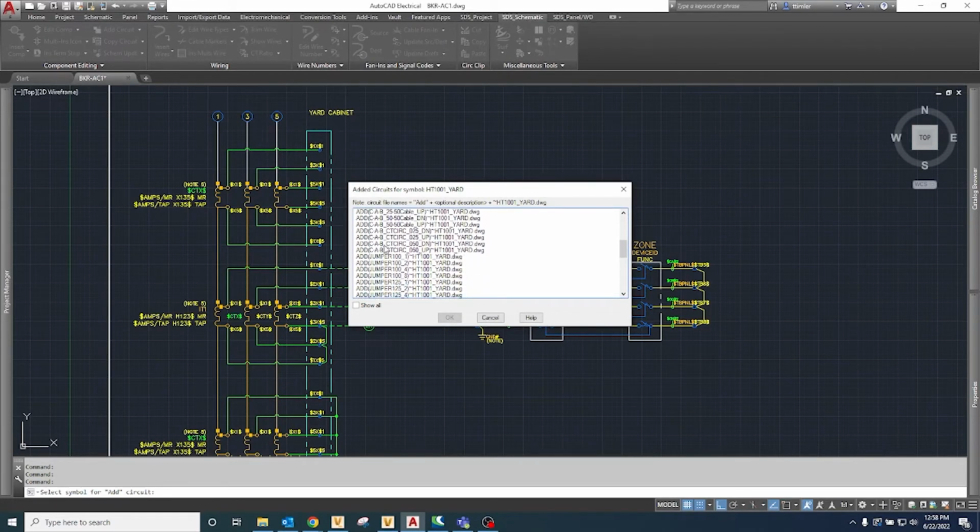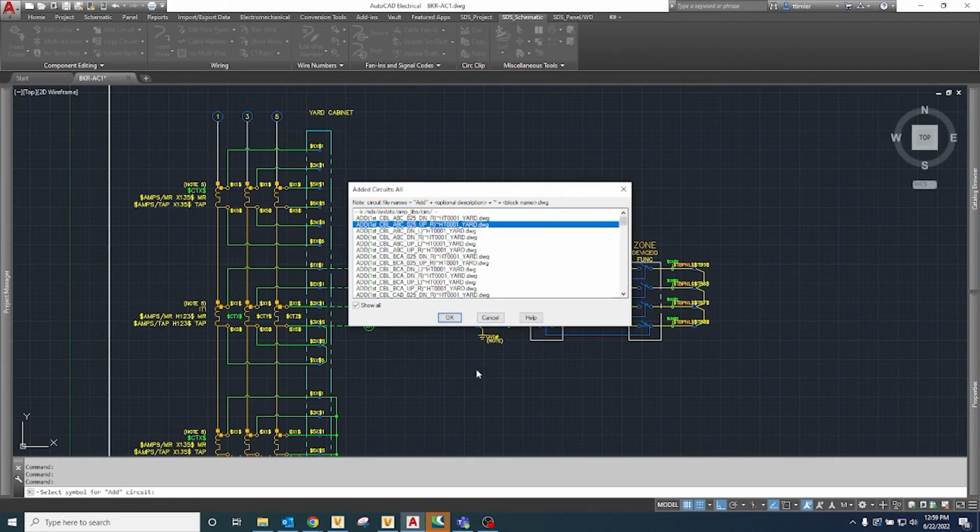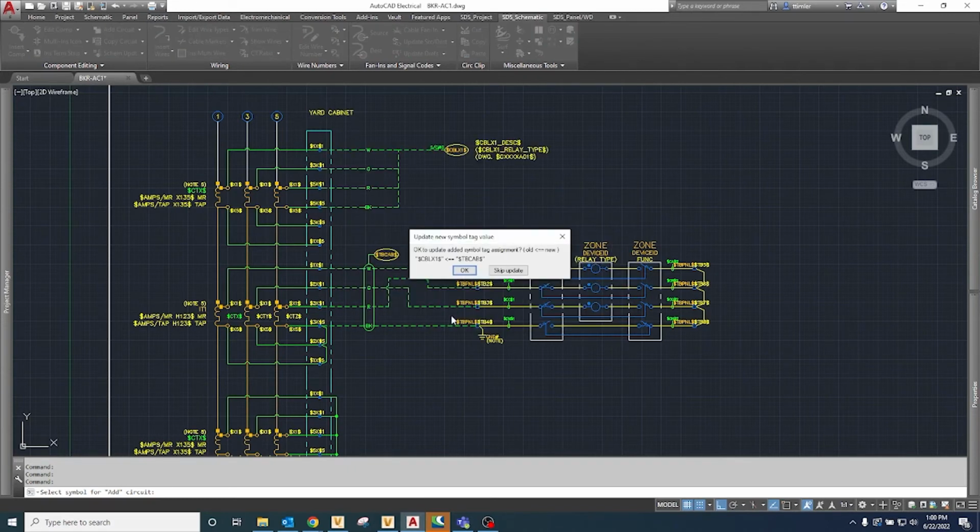You can see just how many options that you can add using this tool: full circuits, cables, and even simple jumpers. Using a standard grid spacing is a key element to making this tool flexible enough for different applications and different standards. We have schematic jumpers for wire spacing from 2 inches all the way down to 1/4 inch. To find the fan-ins, I'll simply select the Show All box and show both the T1 wire change terminals and the T0 pass-through terminals for my schematic terminals. Once I find the correct cable, I can simply snap it in.